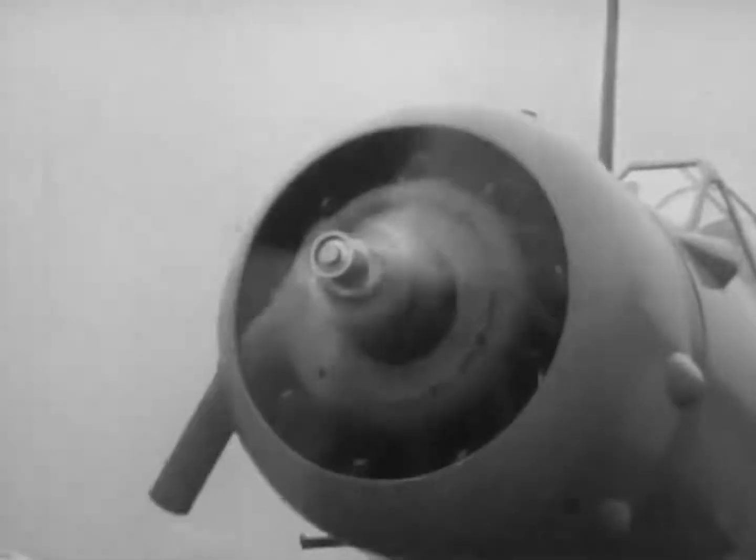This propeller is hydraulically operated by engine lubricating oil. By forcing the oil into the hollow hub, the pitch of the propeller is changed as the cylinder moves forward away from the hub.